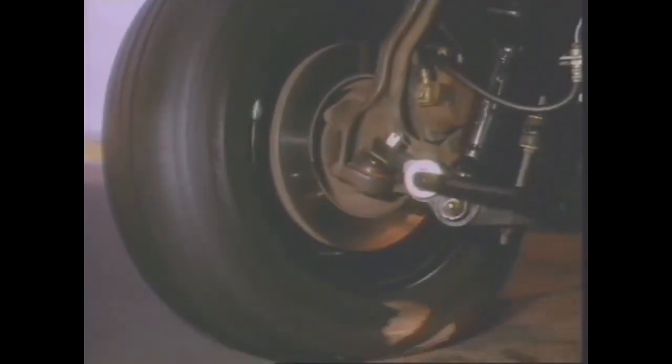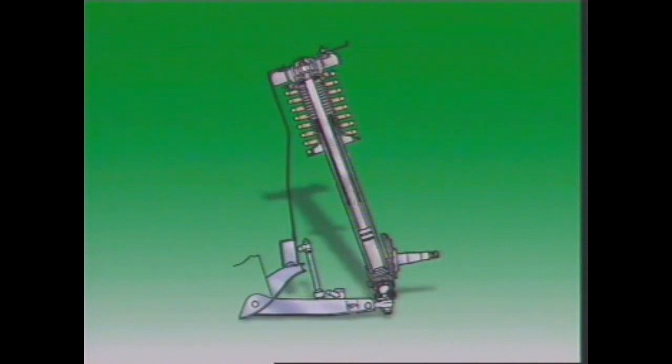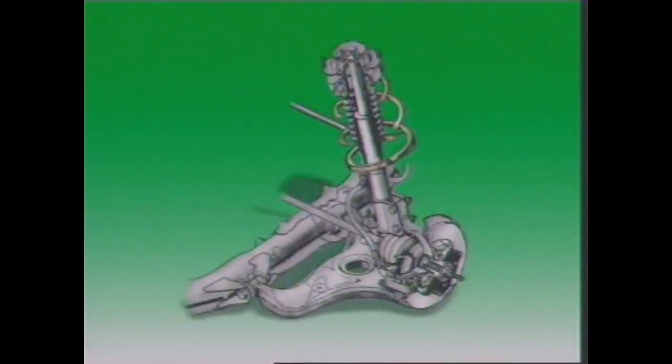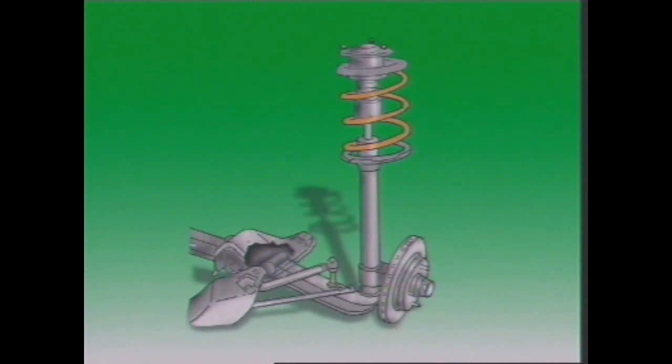The arms must be strong enough to withstand the forces due to normal operation, but light enough to minimize the vehicle's unsprung mass. The front suspension can have 1 or 2 control arms. Parallel link front suspensions have 2 control arms. Vehicles with strut-type front suspension have only 1 arm. It can be a wishbone shape with 2 fulcrum mounting points or straight with single fulcrum.